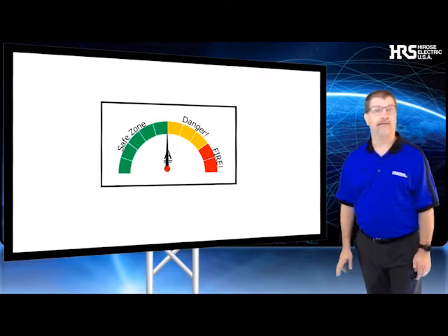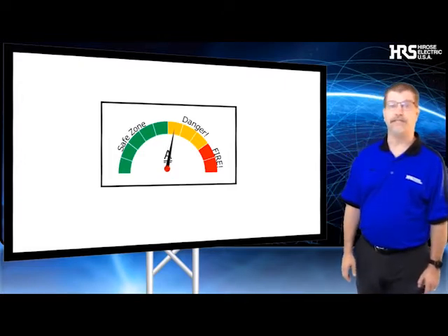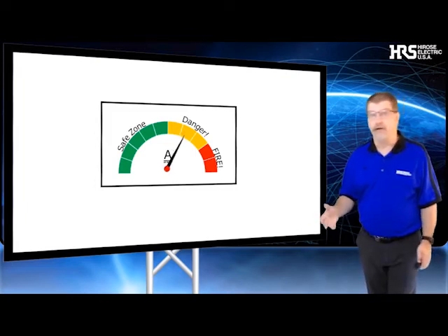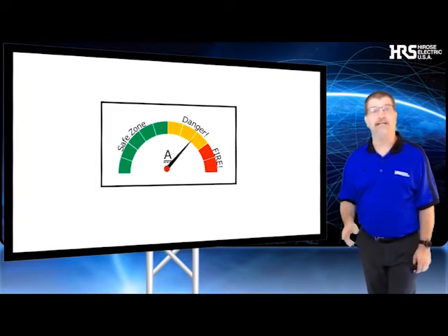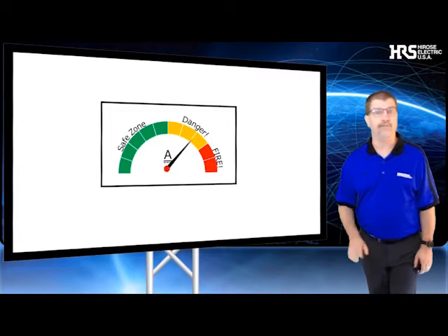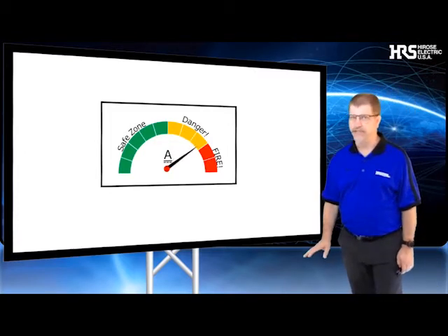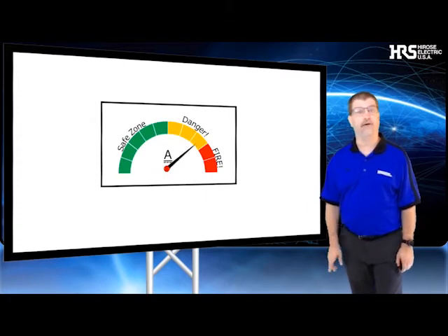How does this impact the rating, you ask? Well, the electrons will travel over the path of the least resistance. This means that contact A may be carrying 60% of the power in our example, 6 amps, and contact B may only be carrying 40%, or 4 amps. Suddenly that 5 amp contact that you initially selected is being pushed too hard and overheating.